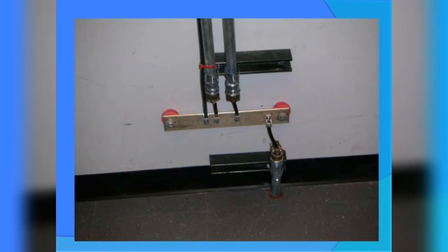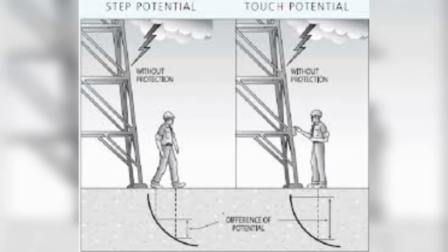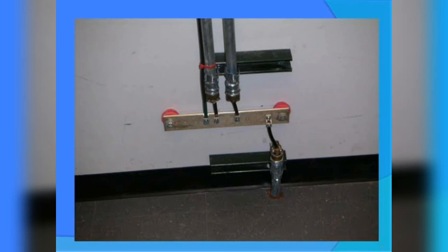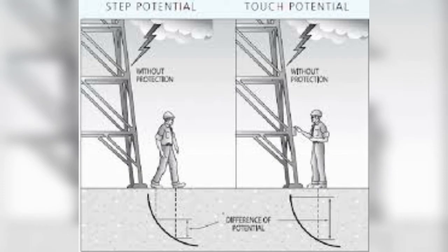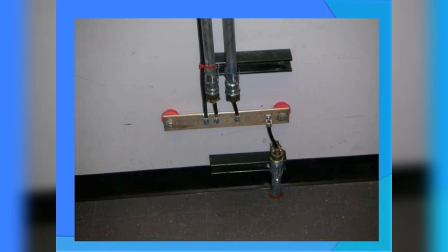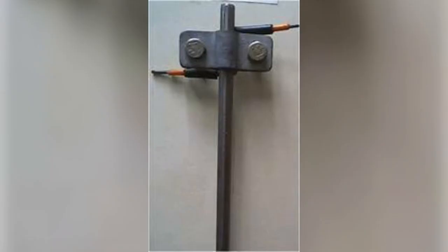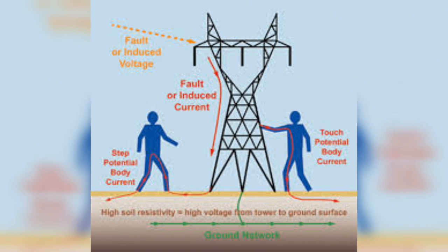During a typical ground fault condition, unless proper precautions are taken in the design, the maximum potential gradient along the Earth's surface may be of sufficient magnitude to endanger personnel in the area. Proper grounding is therefore required for a substation.